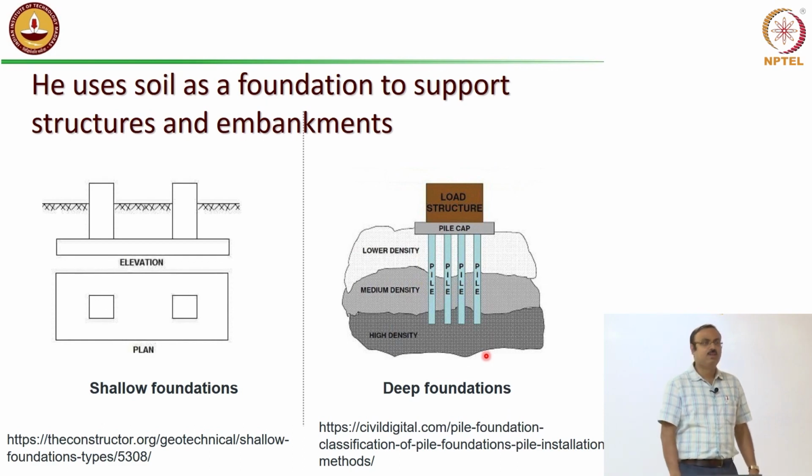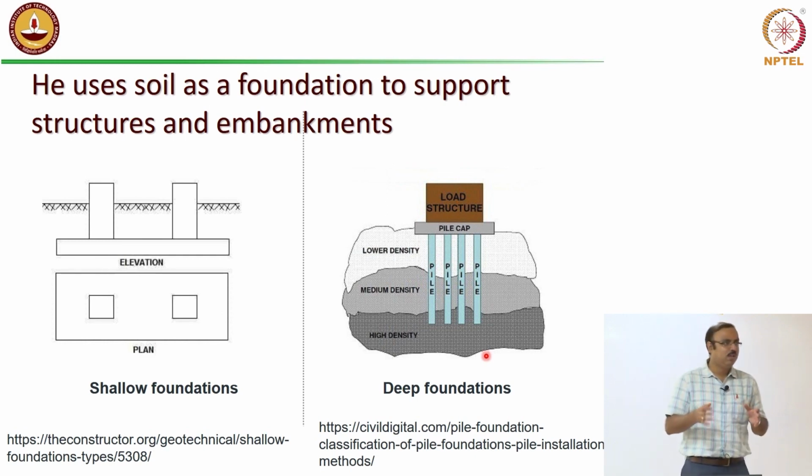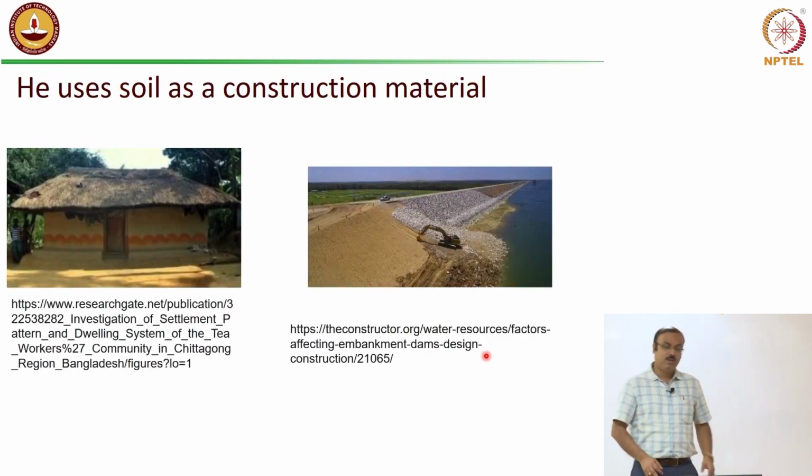Now, this is the first job: the design of foundations, whether shallow or deep, how to design, what should be the depth, what will be the size of the piles. Like you have a 4-leg stool, you can sit, it is safe, but if an elephant is sitting, it may break, right. So, you have to design those legs based on the loading. That is where the size, shape and depth of the piles, everything will be determined by the geotechnical engineer.